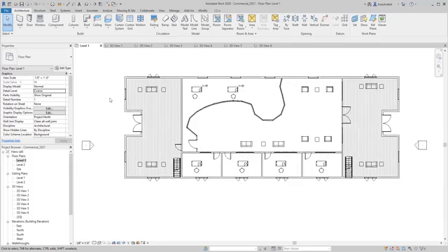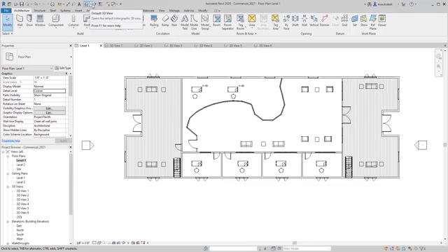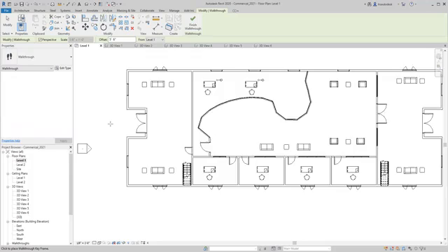So how to create this? Oftentimes it's something more having to do with using Revit. When you're in Revit and you're using, for example, the default 3D view, you're up here, you can scroll down and go to where you see walkthrough. That changes your properties browser to a walkthrough. So when you do that,